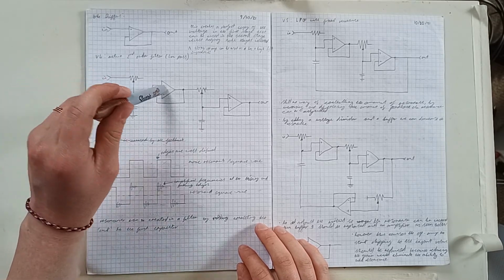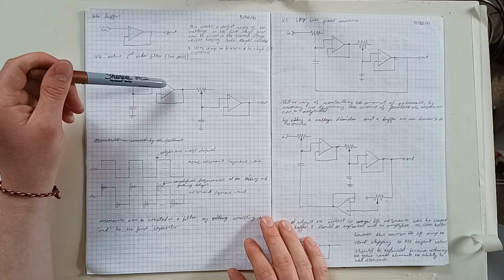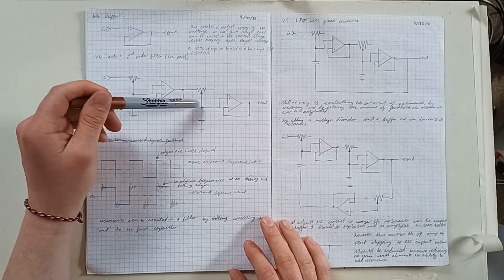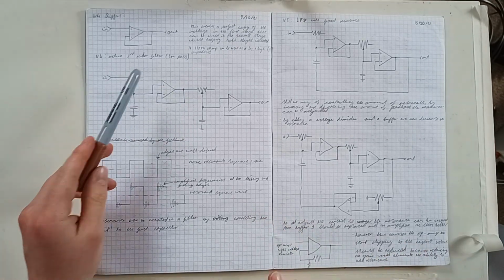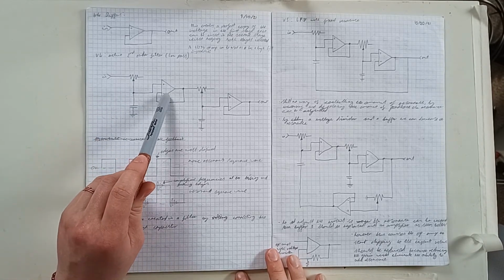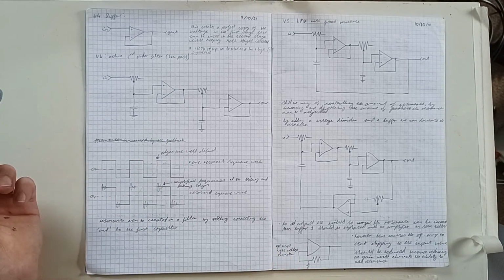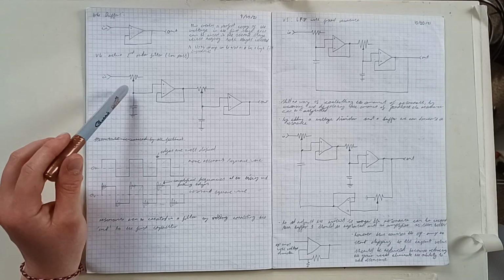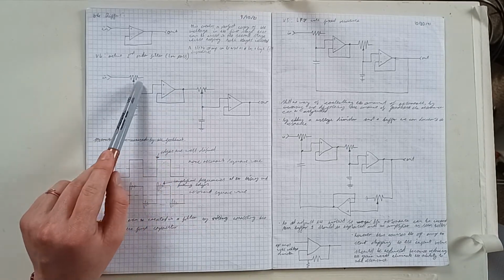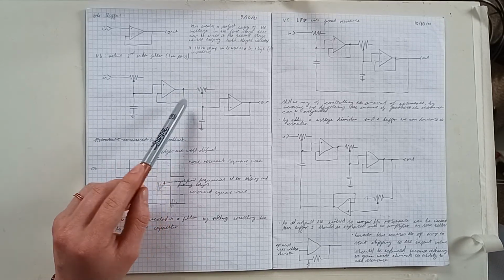And the buffer prevents this because it essentially copies your input into the non-inverting input to the output, preventing any crosstalk, because the op-amps I was using had a very high impedance, which is a form of resistance for AC currents, reducing the actual connection between these two points while still having identical signals.